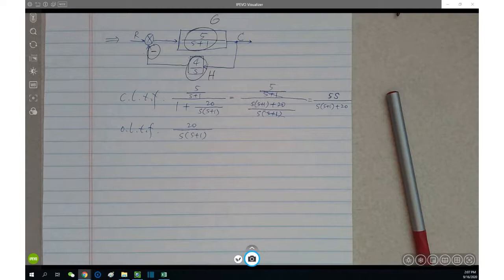Fourier transform is more of signal analysis. Given a signal containing multiple different signal components, say DC, AC, and inside of AC you have fundamental and harmonics, a kind of mixing signal, and you are looking for the magnitude of each component. You can conduct Fourier transform.